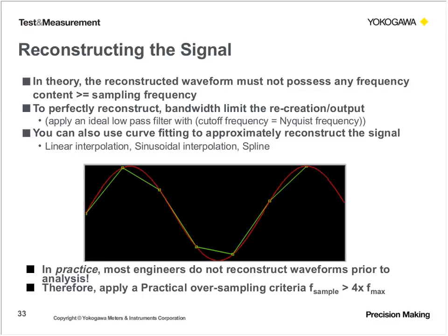You can also try to sample at a smaller rate and choose maybe a special type of interpolation to connect the dots a little bit better in that last example. But that's not always a guaranteed method, and again, it's difficult to calculate the accuracy in those cases.